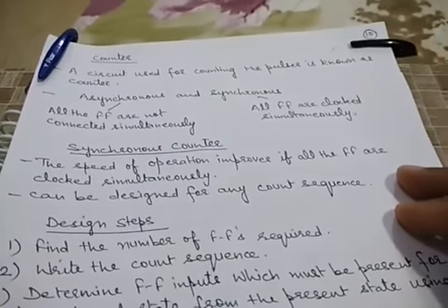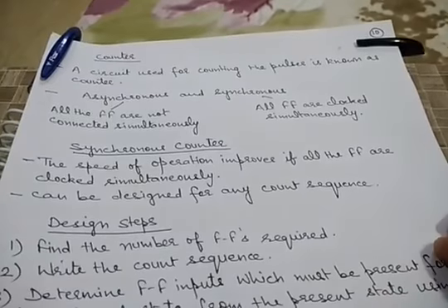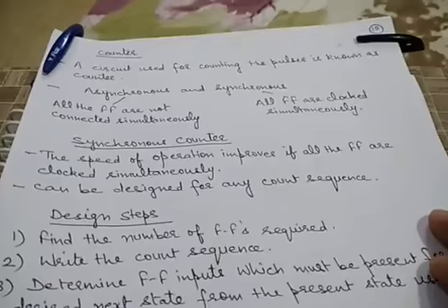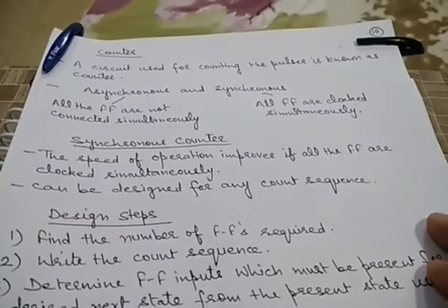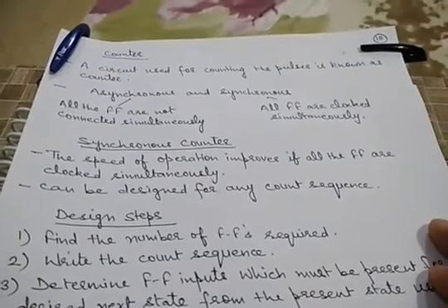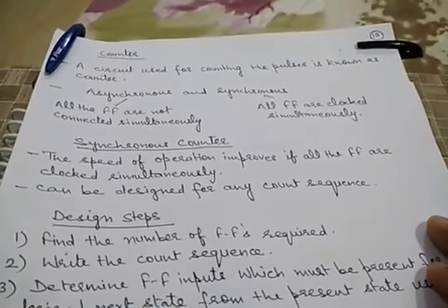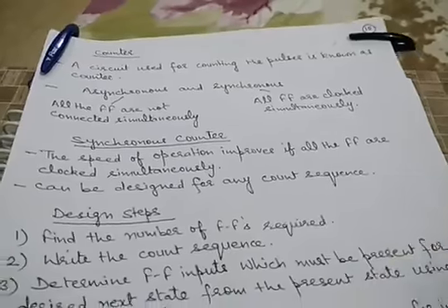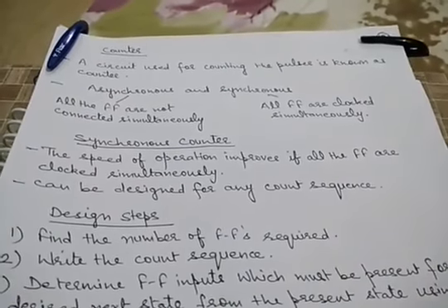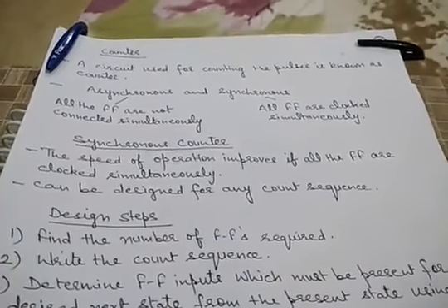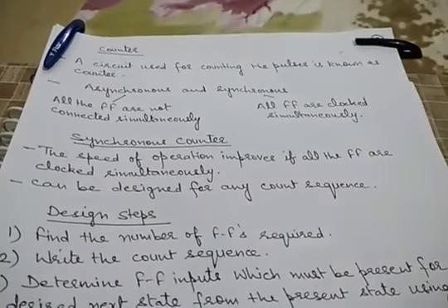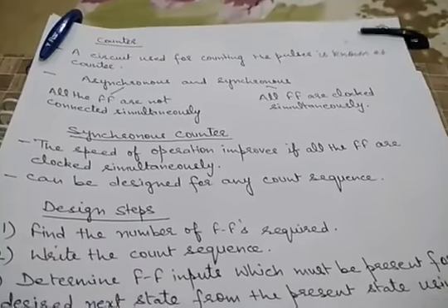Now in this lecture I will be going to discuss about synchronous counter, like what is synchronous counter and how to design a synchronous counter. The first thing is the advantage. Like I have told you that all the flip-flops are clocked simultaneously, so the speed of operation improves. Second is it can be designed for any count sequence. Like if I want to count 1, then 3, 5, 7, or I want to count the sequence like 8, 10, 16, 21, then I will be applying those sequences only, and then I will be making a counter.